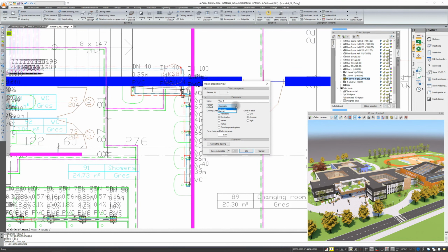If you have a lot of views, some levels, some cross-sections, axonometry, and extensions, the program starts to run slower because each element to introduce has to be redrawn on each view. When you switch the refreshing in the view to manual, then the given view is not refreshed, so the program works faster. But then if you insert a pipe in the view, and you have set in axonometry that it does not refresh automatically, only manually, you have to refresh the view to see this tube. Simply switch the given view, so it is better to draw a few elements and only refresh it, thanks to which the program will run faster.